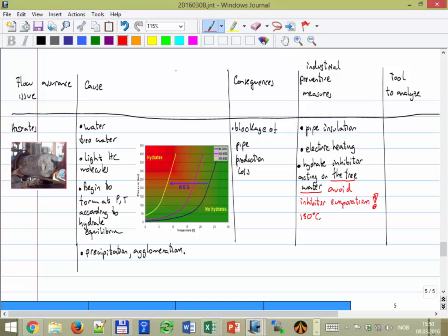So you think, where could I get an increase in temperature? You're saying that we lose temperature, so where could I get an increase in temperature? Compressors, okay, that's very right. In compressors, as you will see later, we will have another session. When you increase the pressure, also the temperature is increasing, and sometimes you may get close to these ranges, and then you get evaporation of the glycol, evaporation of the methanol, and you might begin to have problems, issues.